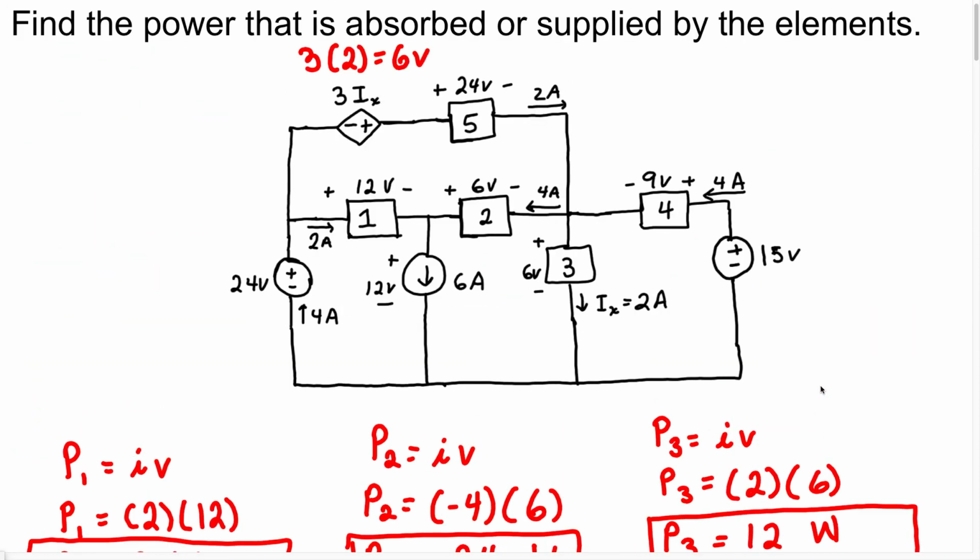So this is how you answer a question like this, but you must be able to recognize when elements are in series, and you must also be very comfortable with passive sign convention. If you get the signs wrong, your answer is going to be wrong.